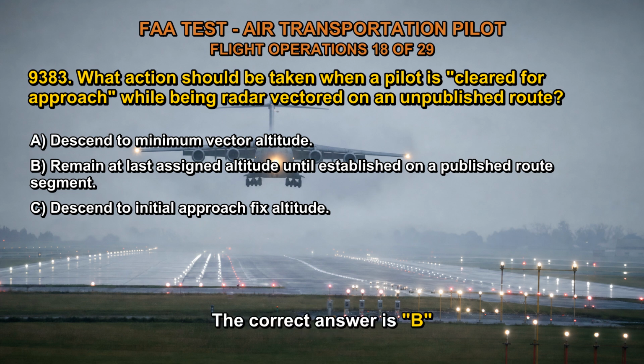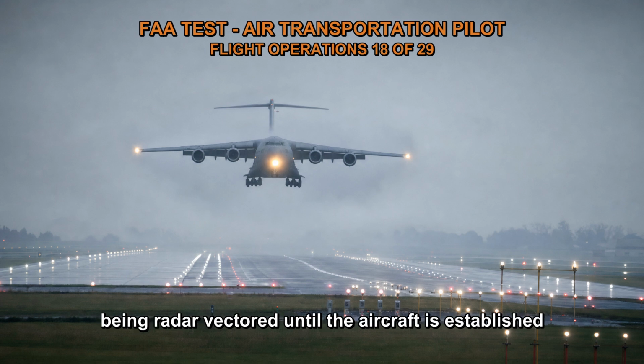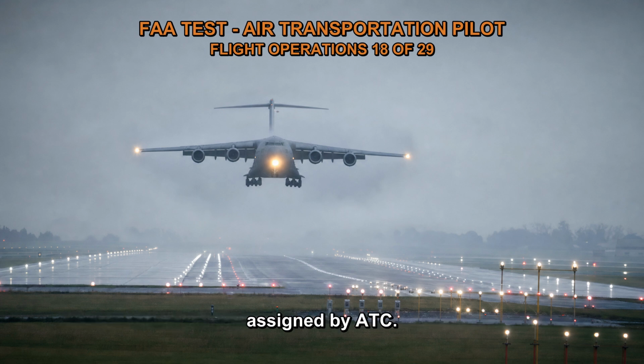The correct answer is B. The pilot must maintain the last altitude assigned when operating on an unpublished route or while being radar vectored until the aircraft is established on a segment of a published route or instrument approach procedure, unless a different altitude is assigned by ATC.